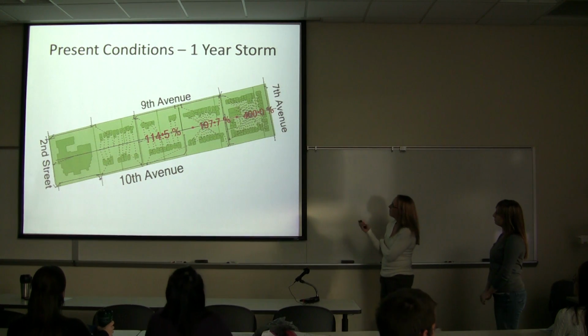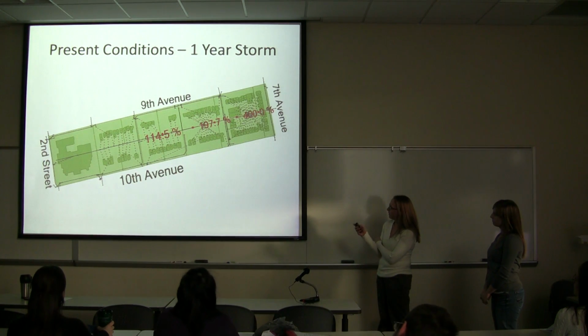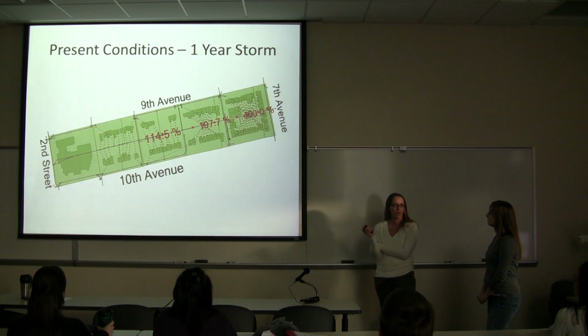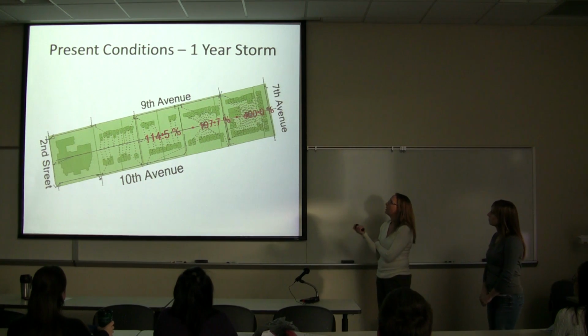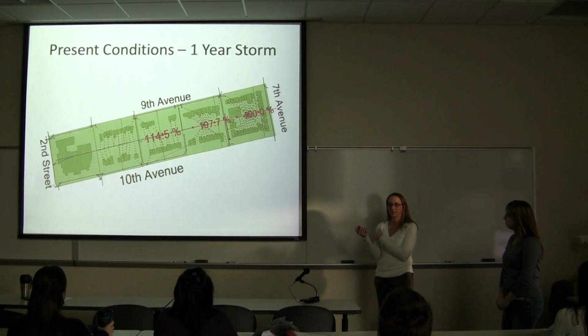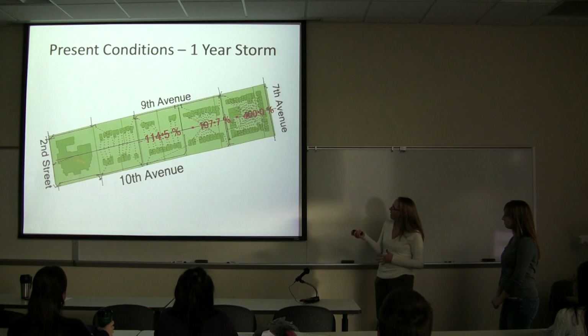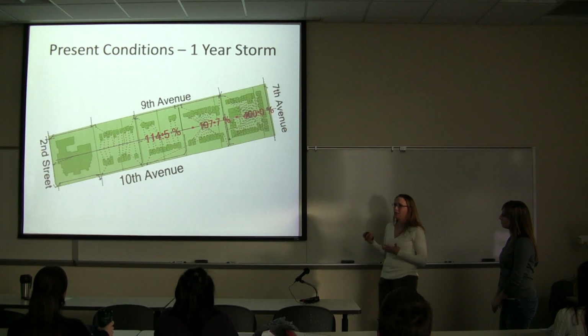As we produced our model, we found that having just a single catch basin was the easiest for keeping the pipe at the correct slope, but it did produce excessive amounts in one location, kind of messing with the model a little bit. So here in the beginning, we tried to kind of separate them a little bit so it wouldn't have such a gush at once, but it messed with the slopes of our pipes so much that for the rest of the network, we didn't do that.